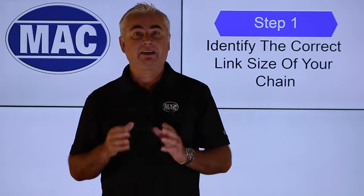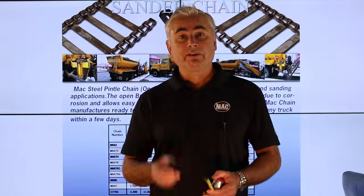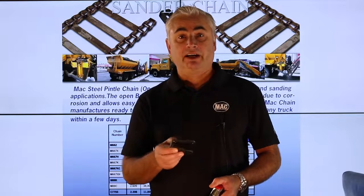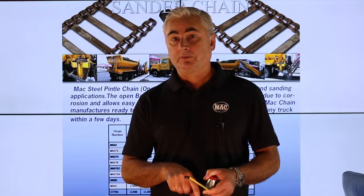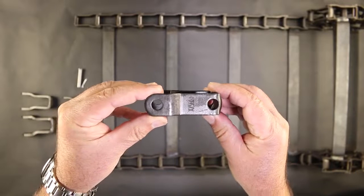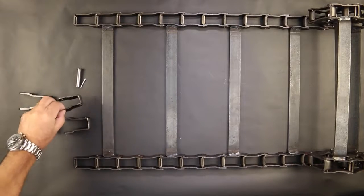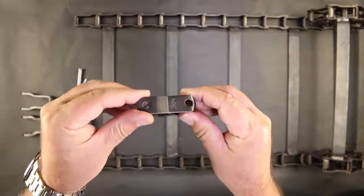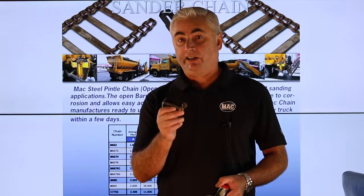Step number 1, identify the correct link size and chain number of your conveyor chain. To identify your link number or your chain style, a lot of times the number is stamped right on the sidebar. In a lot of cases, when your chain is ready for replacement, corrosion has taken away all visible signs of the stamp. So then you have to physically measure the chain to determine the correct chain number.